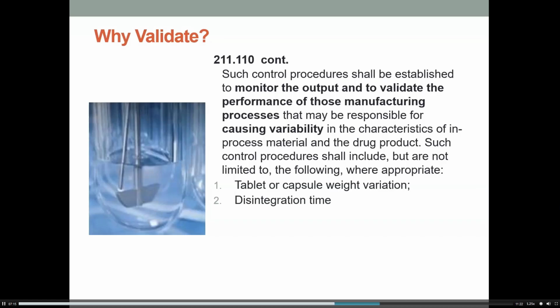The disintegration time is really important because that determines when and where in the body a drug is absorbed. So for specific drugs, they need to have a specific disintegration time. So if your tablet's compressed too hard, or there's not enough of the disintegrant excipient in it, you might have issues with your disintegration time. That would cause a problem.